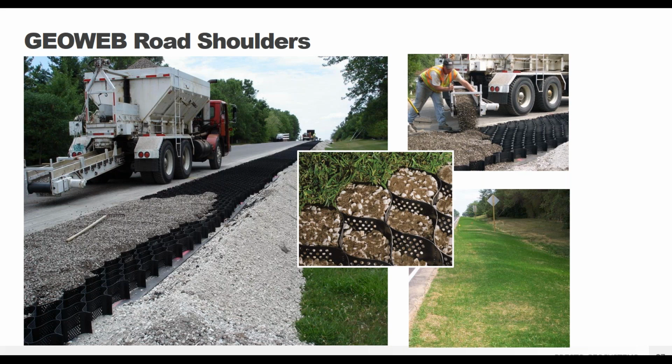So both infill types can widen your roads for emergency access, and they can help manage stormwater runoff from your impervious asphalt pavement by catching that surface runoff and allowing the stormwater to infiltrate naturally and reduce erosion concerns along your pavement edges.